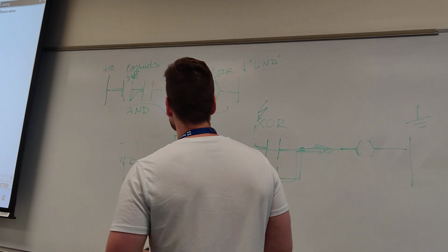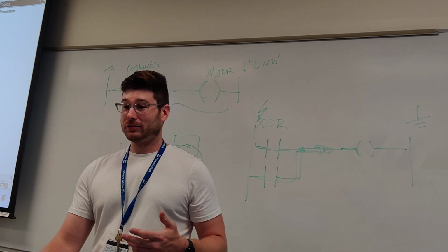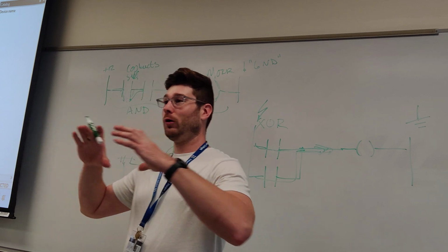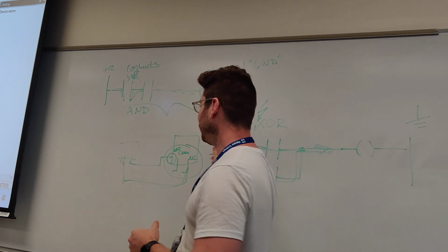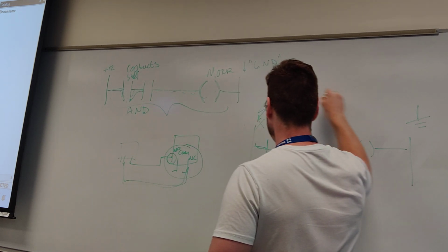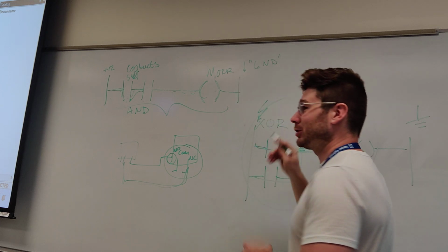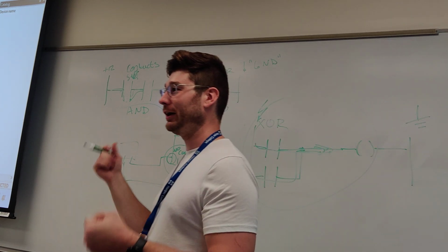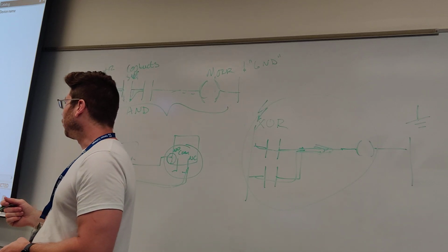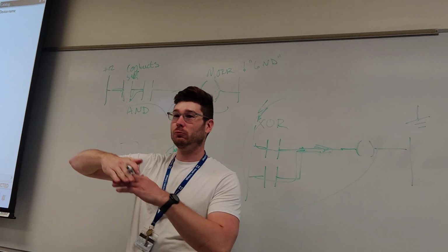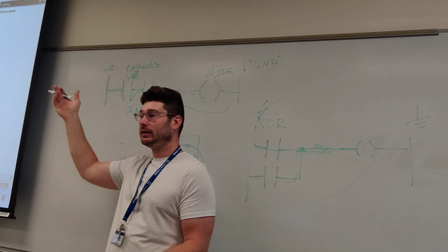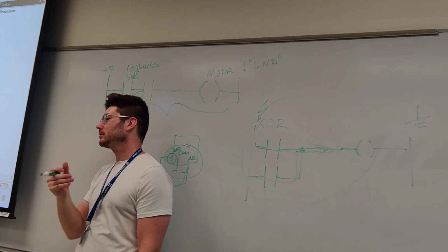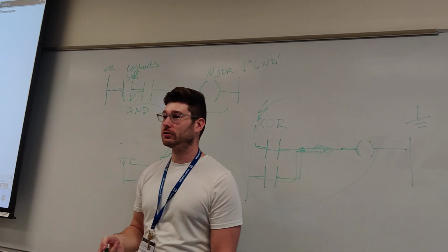You really have the choice of creating one massive network in one rung. There are ways to mathematically simplify logic into minimum gates if you want to do it that way, taking just one or two rungs. Or you could take 20 rungs and make it really simple, with one or two elements in each, and as long as the logic plays nice and does what it needs to do, that's just fine.